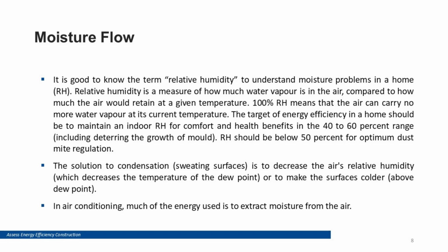Moisture flow. Moisture control protects both health and durability. Condensation risk increases when humid air reaches cold surfaces. Effective control includes limiting air leakage, using suitable vapor and moisture layers, and ensuring assemblies have a safe drying path. This keeps insulation effective and reduces mold risk.